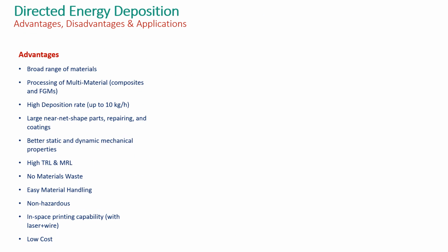There are several advantages with the DED technique. DED is basically used mostly for metal-based deposition, because we are discussing metals and alloys here. The advantage is when we compare it with another AM technique used for metals and alloys, that is, the powder bed fusion technique. Compared to that, it has a big advantage because we are using bulk material, so we have the freedom of a range of materials which we can use.